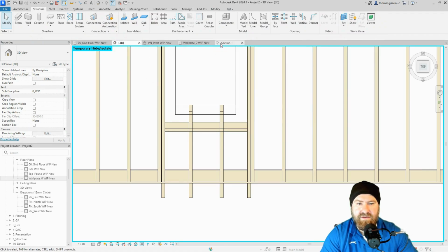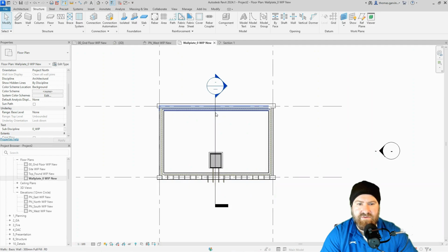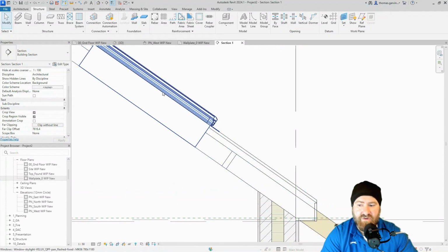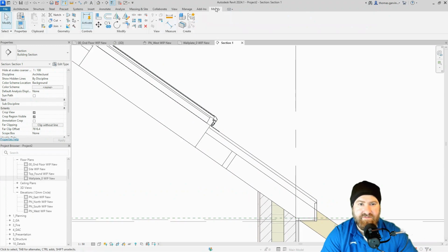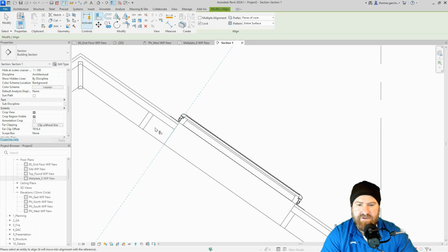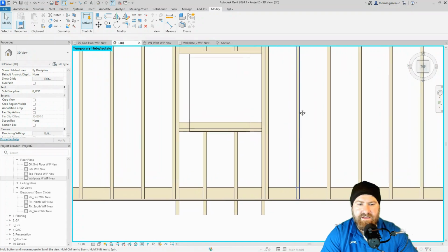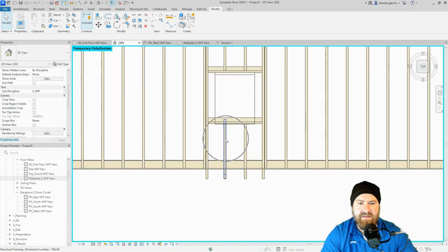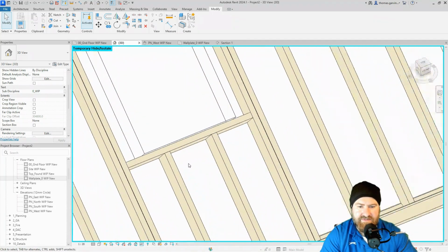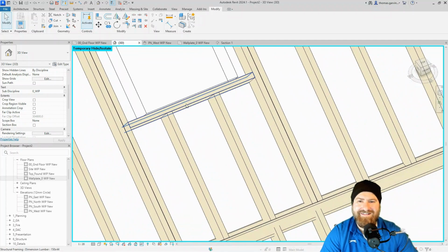So if we go to the wall plate plan and put our section through the window, which it is, I can then align and lock those trimmers. Okay, so modify, align to the opening, tab, and lock. Align to the opening, tab, and lock. Perfect. Go back into 3D, and you'll see that the rafters are now neatly trimmed to the trimmer.